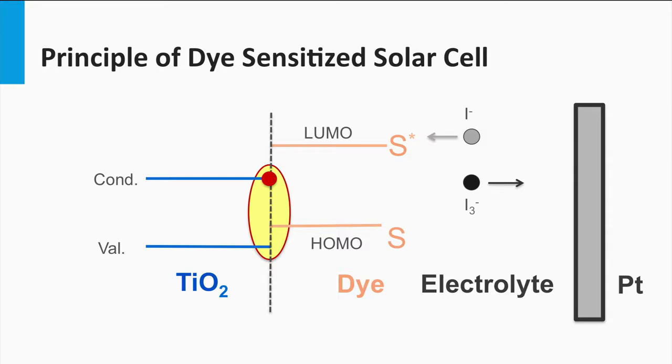The photosensitizer molecule remains like a positively charged entity. The electrons in the titanium oxide move to the TCO-based back contact. The transport mechanism is diffusion-based. The electrons diffuse between the various titanium oxide nanoparticles until they arrive at the TCO contact. Through the electric circuit, the electrons move to the counter-electrode, in other words, the other contact.